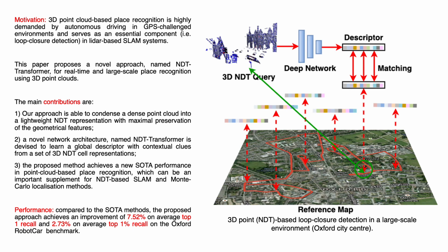3D point cloud-based place recognition is highly demanded by autonomous driving in GPS-denied environments and serves as an essential component in a LiDAR-based SLAM system. This paper proposed a novel approach named NDT-Transformer for real-time and large-scale place recognition using 3D point clouds.